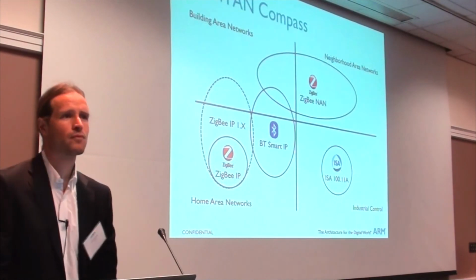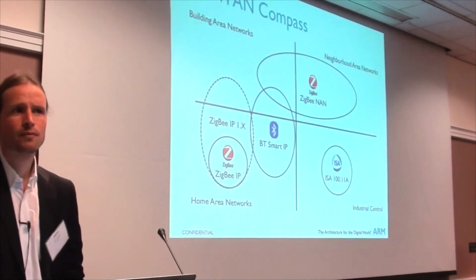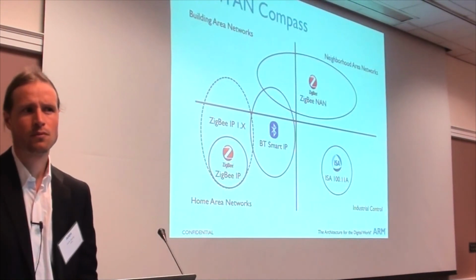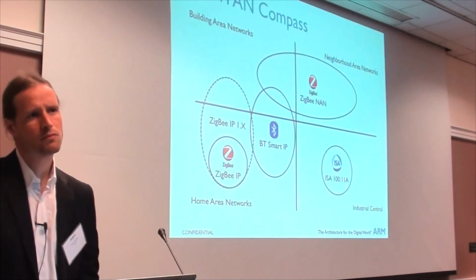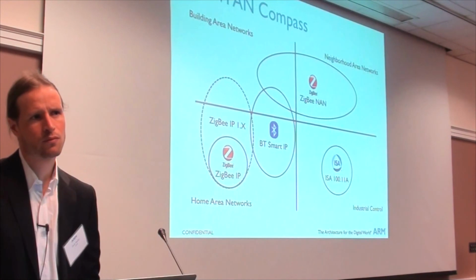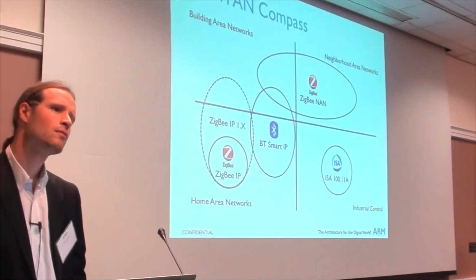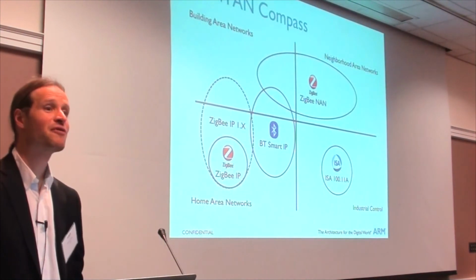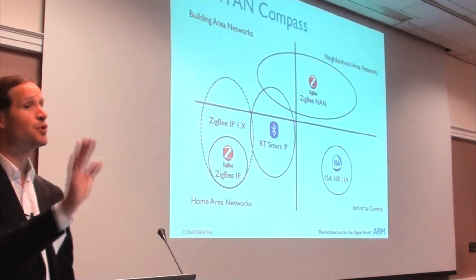Yeah, so the case was actually the software was the same, but the chips were different. The chip maybe was different, a different radio, but the 6LoWPAN stack and the routing part was the same. Ah, but the 15.4 settings were different. Absolutely.